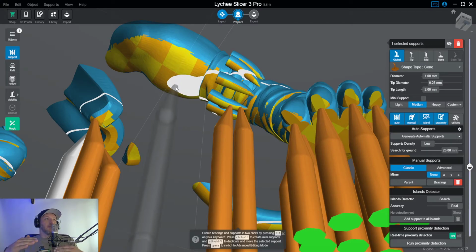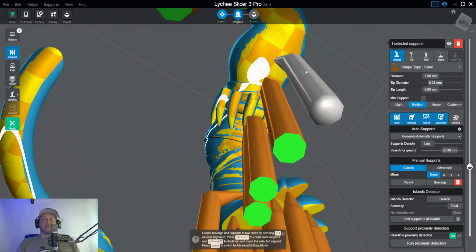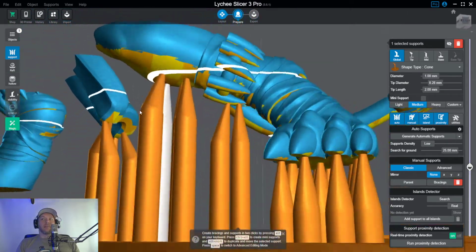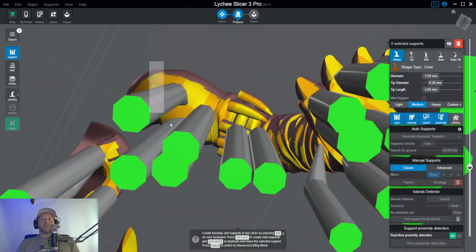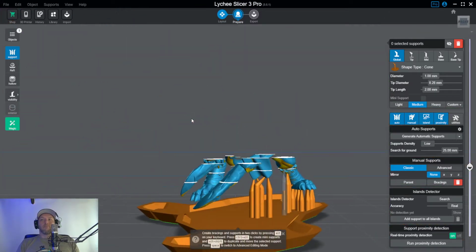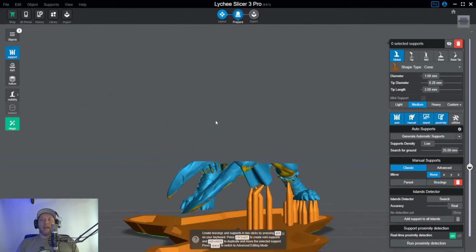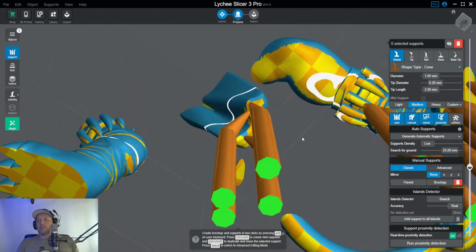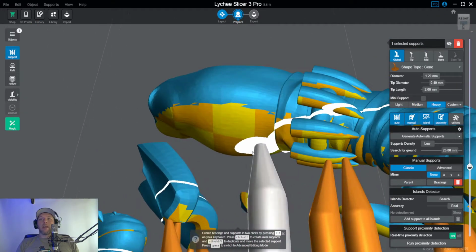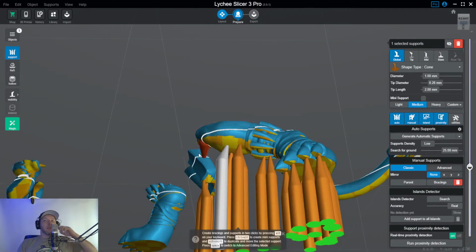Because of that parallel mesh, it's going to act very much like the cube we just talked about. When it's turned on its face, it's going to pull a lot. And so in order for us to make sure that this actually prints the way we want, we're definitely going to want to add a couple of supports here. Now, could we do this with 1 heavy or 2 heavies? Yeah. I'm using the wrong keys here. Sorry. I think we could, but then I worry about putting that pockmark on the model. I'm more comfortable adding 4 mediums than 2 heavies.